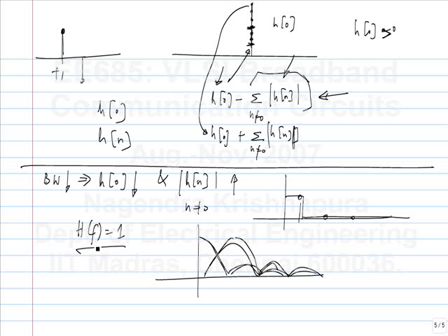Now let's imagine some h which has a large bandwidth, but not infinite. So some of these higher order lobes will get attenuated. So the sum will get disturbed slightly, right? But then if the bandwidth of h of f becomes a significantly smaller fraction of fs, then you will have something like this that affects the main lobe itself. Then the summation is severely affected. So as you increase the bandwidth, it will get better.